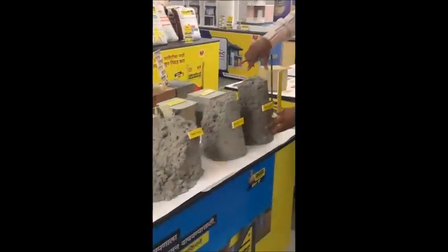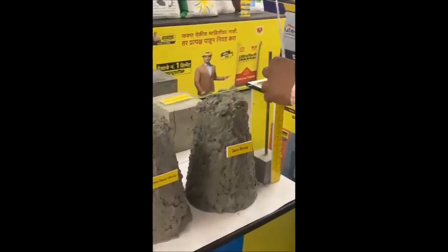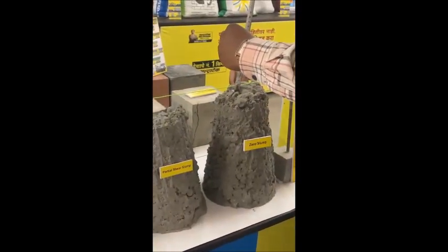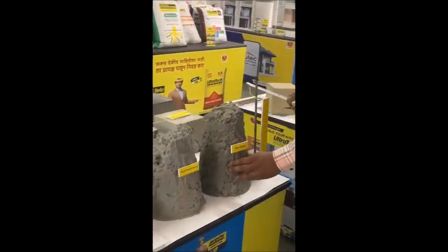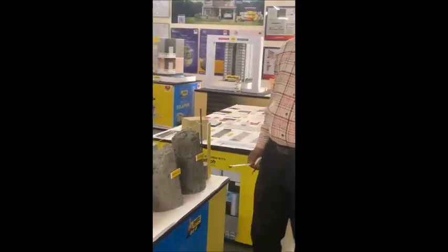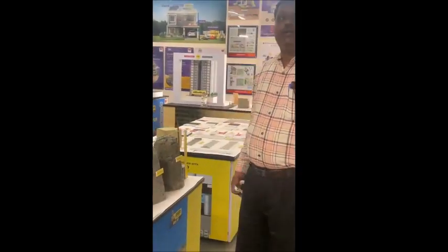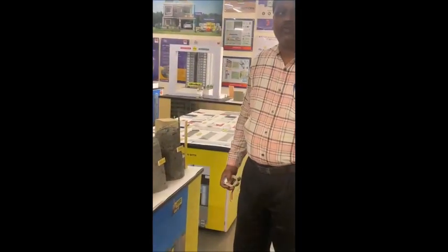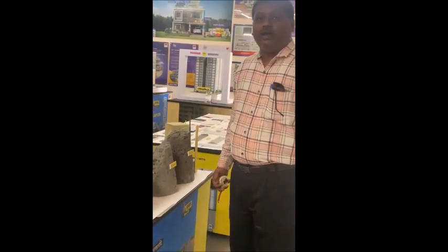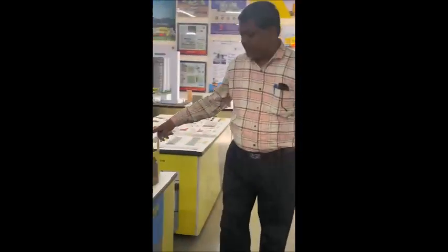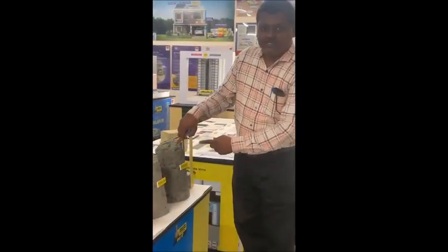If you see the first concrete, if I measure the slump from the top of the cone, it is 0 or only about 10 mm, which is actually the nature of concrete 0. But the 10 mm value matches this table, the table of IS 456 which I explained at the start of this video, in which very low slump concrete is specified for pavements using pavers. So whenever this type of concreting placing condition is there, you should go for this type of concrete, which is also known as zero slump by nature.